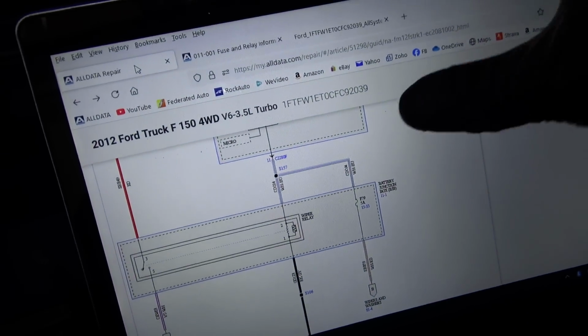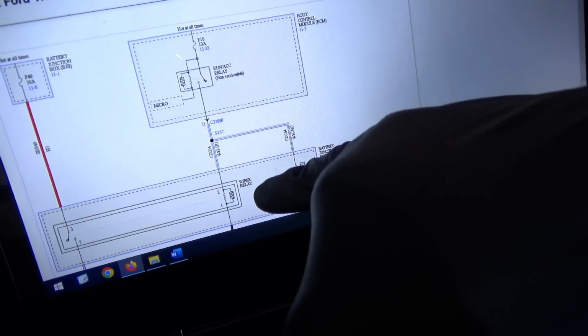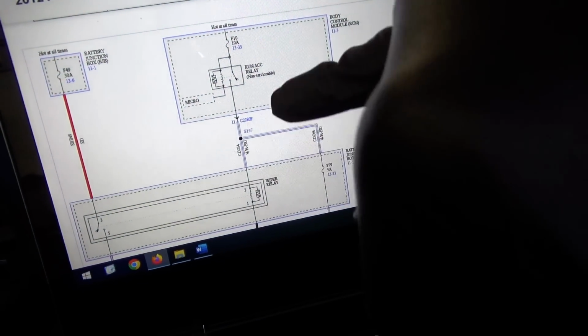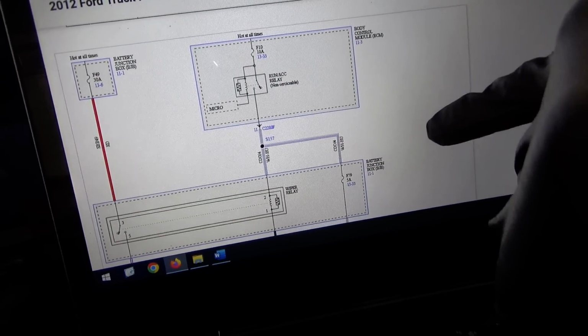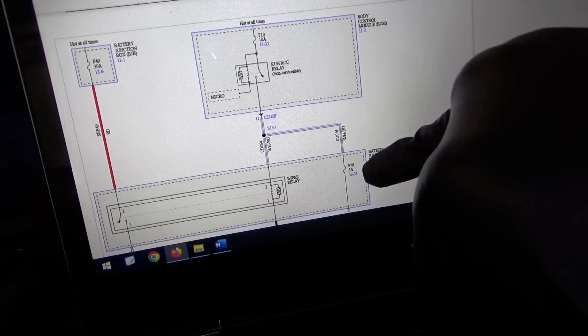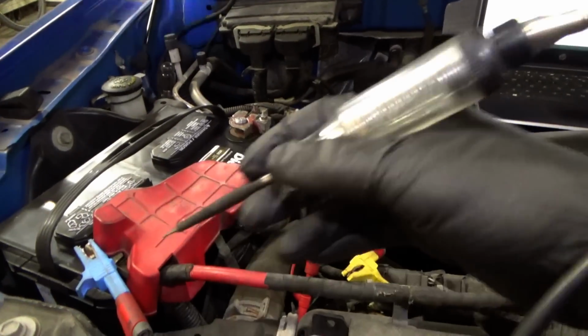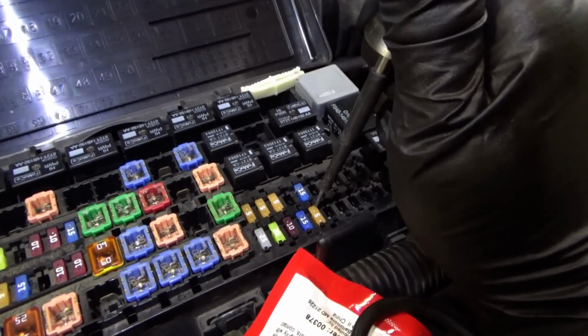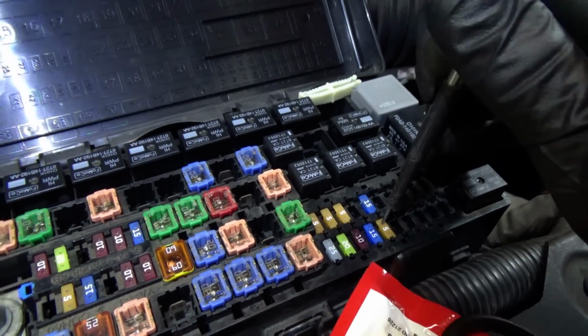White and blue wire. That's the output of the run accessory relay from the BCM. Well, here's a neat trick you can do with the test light. Since both fuse F79 and the wiper relay control are on the same circuit and they're not being energized by the BCM, let's take a test light from battery positive, plug in the relay, and feed some power to fuse F79, 5 amp. So, relay's plugged in. I'm on the battery positive with my test light. If I touch fuse F79, check it out. The wiper relay is clicking.